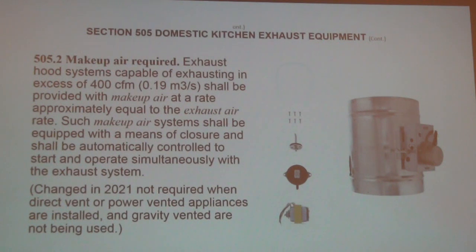But the more inexpensive dampers they use, what do they got, duct tape on them or something? Yeah, just a little flapper in there. Flapper, they will not work. They're not sensitive enough. So a lot of heating contractors in my jurisdiction will use an electric damper for that reason, because they cannot get the barometric to work.